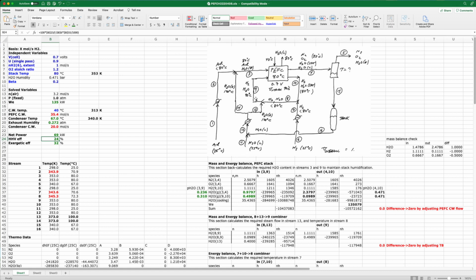Since we have to humidify all of these gases, we have to generate a lot of steam in stream 12 to be able to do that. Because the saturation pressure is so high, we're talking about half an atmosphere basically, half of our gas is steam. It means that streams 10 and 4 are carrying enormous amounts of gaseous H2O, which has a very high enthalpy, but it's only at 80 degrees. So it's very, very hard to recover the thermal energy contained in that steam.